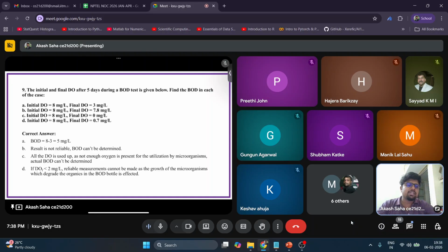Many times when industrial samples come, we generally don't know how much BOD is there. Even after doing the COD test, we are not able to predict the BOD value at the first trial itself. That is the problem, because industrial samples are mostly chemicals, so the COD will be very high but the BOD will be very low. It doesn't always follow the 60 to 70% ratio.